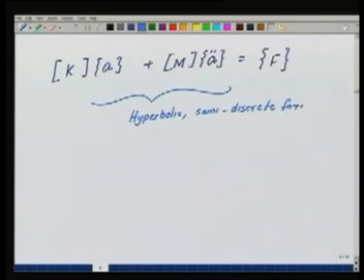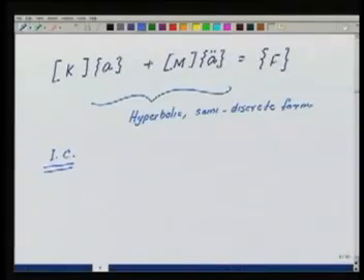Okay. What are the boundary conditions? As before, the boundary conditions are either the displacements or the forces at the ends. Now this problem will need initial conditions. So the initial conditions for such a problem, for the second order problem in time, will consist of defining what is the displacement at time t equal to 0 and what is the velocity at time t equal to 0.